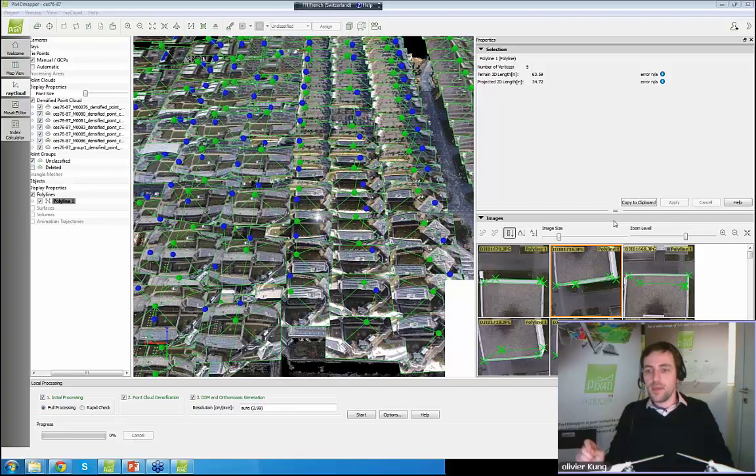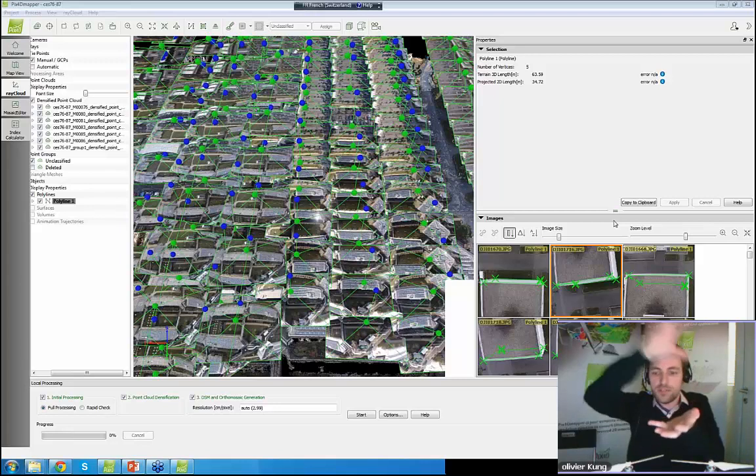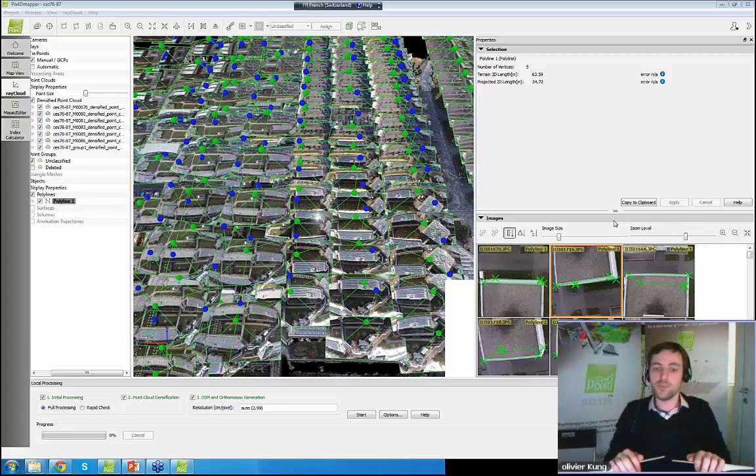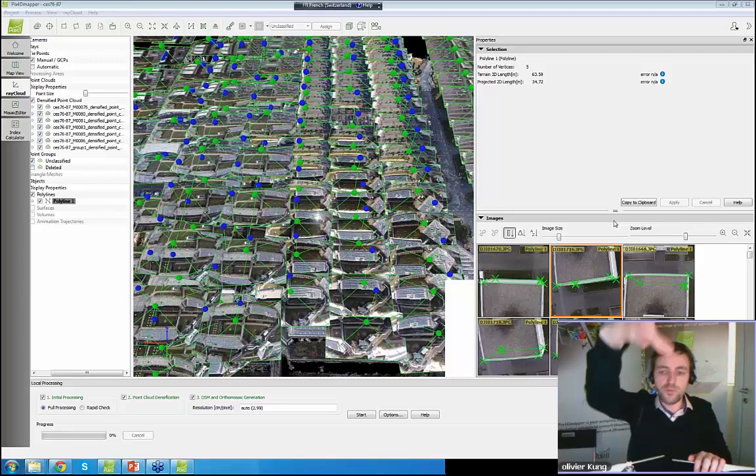This way we avoid something which is really bad for 3D reconstruction, which is when you have a ton of images in the same area and you have a blob of images. This actually makes a lot of errors and makes it much more difficult. So by doing this, we make sure that every time you move the drone a bit further away, a picture is automatically triggered.